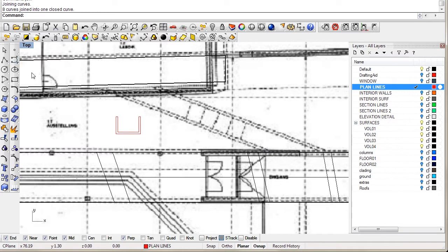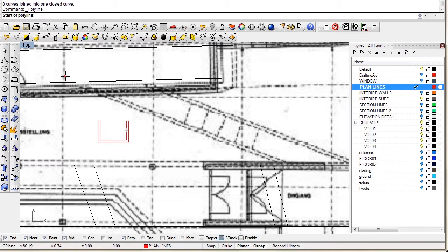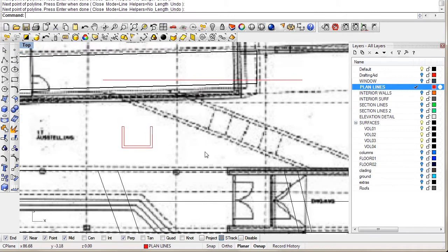Looks pretty simple. And then the other thing we need is the lines, the lines that go all the way through. I don't want to draw these lines diagonally. I want to do them straight first, because I want to put several control points, at least one here to do the inflection. So I want to do something like a straight line with Shift and Alt selected, not to snap on anything. I just want to do control point, control point, and the end of the line.